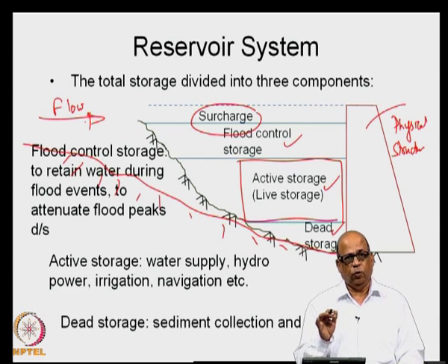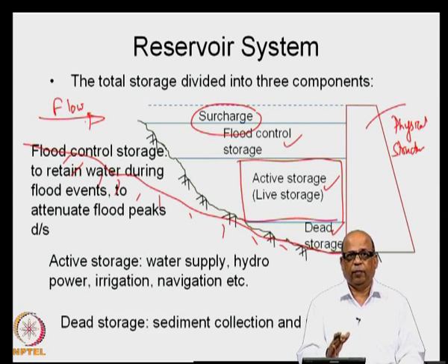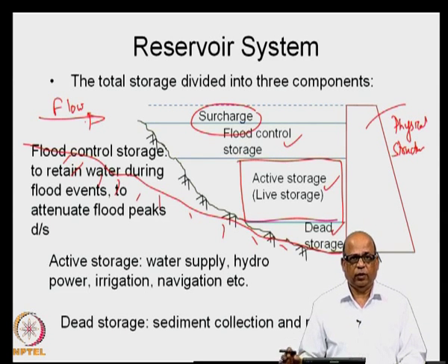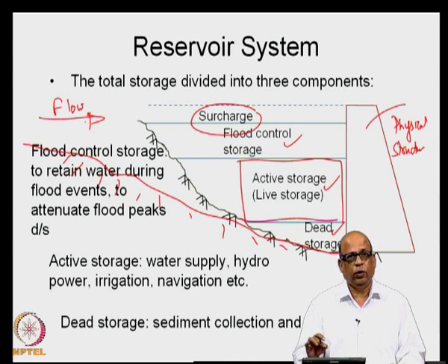Okay. Within this framework, we are now talking about reservoir systems with deterministic inflows. That means the flow sequences are all known, given. Now, these would be typically historical observed sequences. Let us say you have the last 30 years of data on the flow that has occurred. If you have a reservoir that is already in place, you would have measured the flows which are coming into the reservoir and called them inflows to the reservoir.